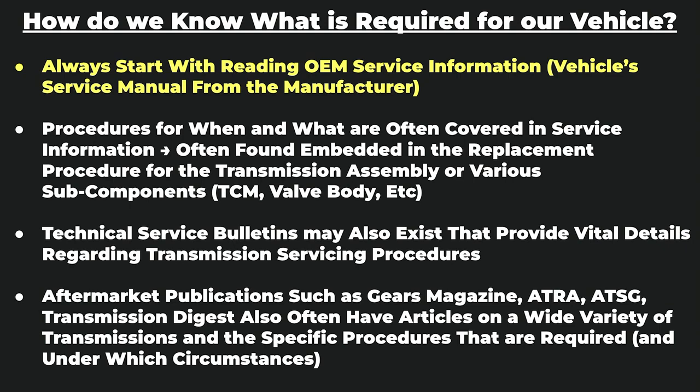So again, there are many strategies to find the information on what is required for your vehicle. Always start with the service information as your first point, look at all relevant technical service bulletins as option 2, and check the aftermarket publications or other publications I'm not aware of, but again, these are just some places where you can start.